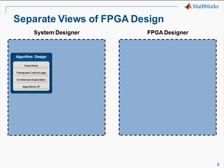The system designer is centered on the development of the algorithm, usually starting off with a floating point algorithm and then converting it into fixed point form. The designer will be concerned with timing, with integration of control logic. They tend to be concerned with evaluating different architectures, different possibilities, different types of FIR filters, for instance. They also need to integrate in existing algorithmic IP with any new content they're producing.